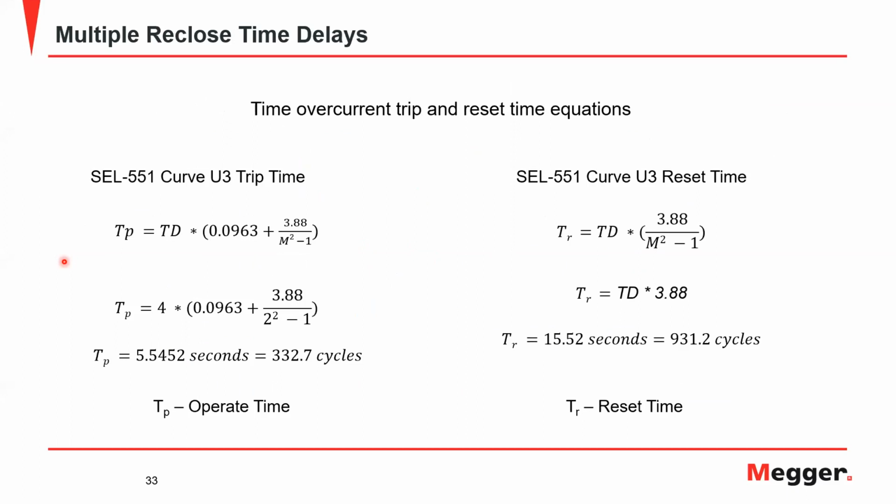So the U3, it stands for one of the types of curves. It's a time current curve that is based on the IEEE standard. And it's present as an option in the relay curve settings. So Mike used this curve in his slides for explaining his examples.